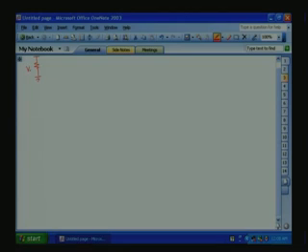So, this is our V0 reference, that is the one we want. This will be given here, then we will be comparing with a feedback voltage, that is V0, then we will give to the current controller. So, this is our controller, this we have to design now. This controller output will give our IS reference.